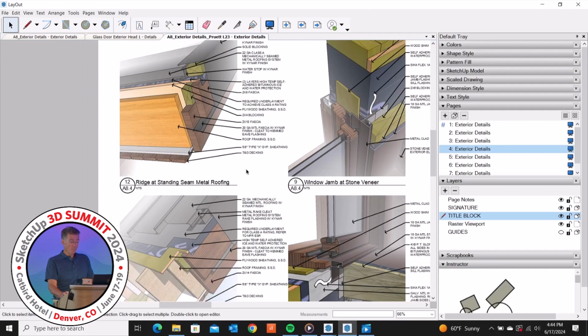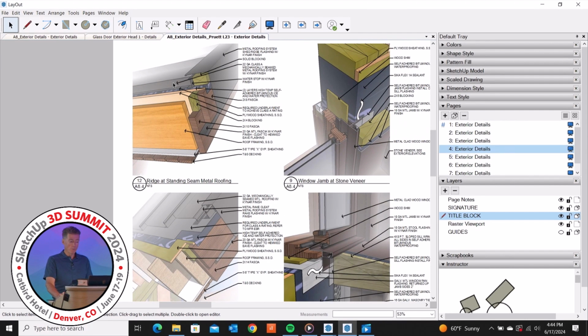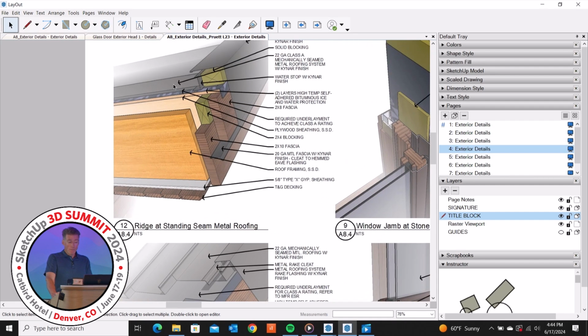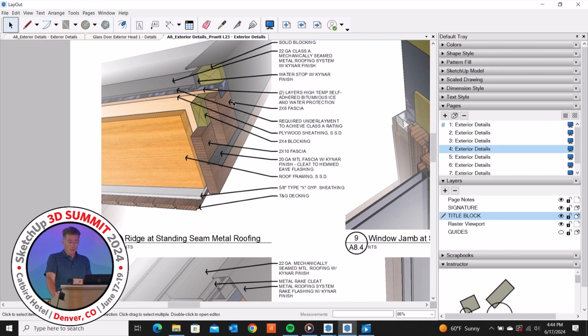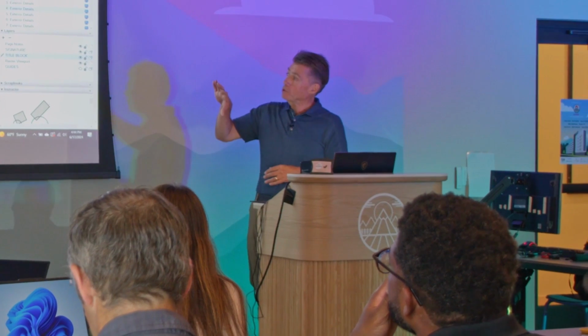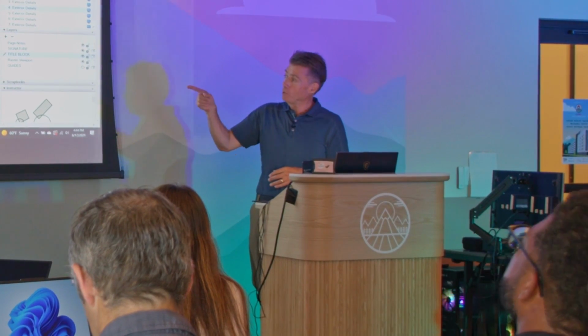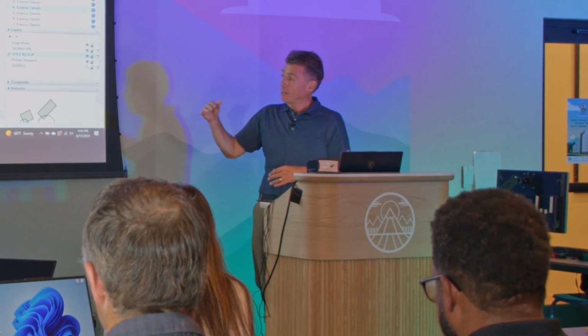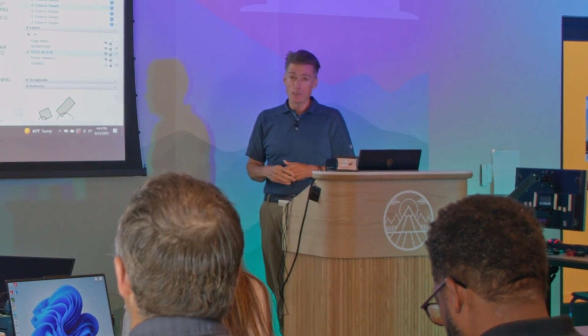And so we have a contemporary, sort of contemporary, traditional, called transitional design. That has, in this case, it's got a shed roof. And so this shows how that shed roof is being designed. And in this case, we did kind of a partial coverage of metal. So the top fascia is completely wrapped in metal with a small cleat below, and then it transitions to wood below. And again, you can see the fire rating that we deal with, the 5/8.